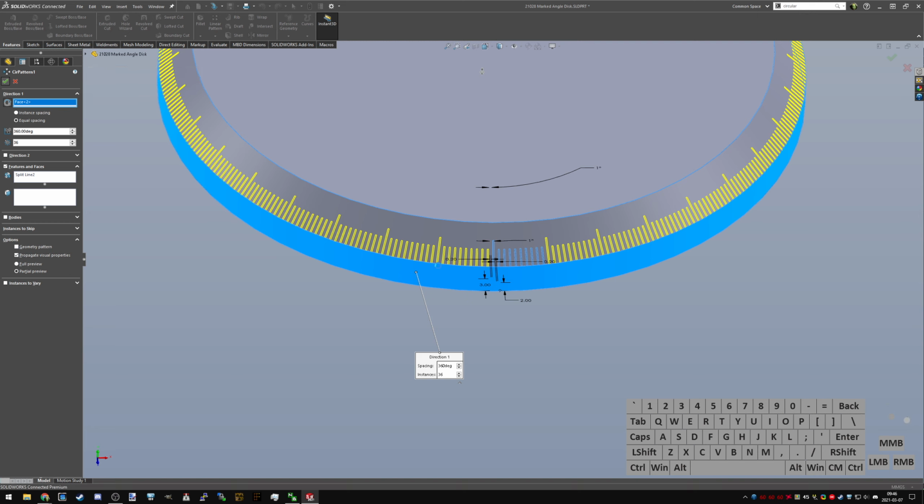I want to split the face like 300 times. This will cause your rebuild times to be really high, but it is a way to get those features marked. Perhaps a second sketch pattern of the original sketch pattern inside there would be better, because then you don't have to repeat a feature 36 times, but it's kind of a trade-off. I'm not really sure the best way to do this efficiently.